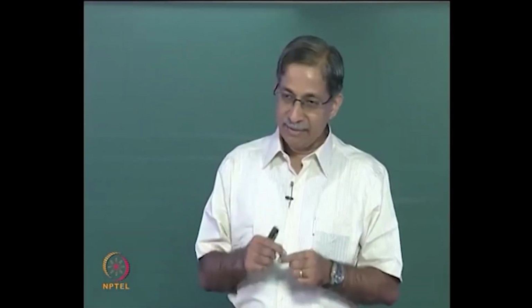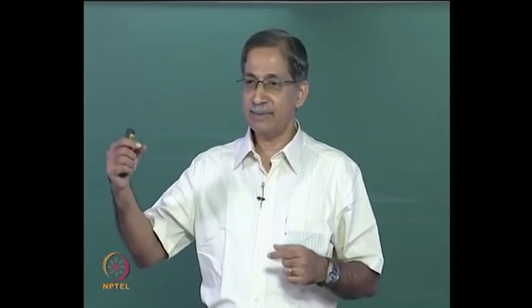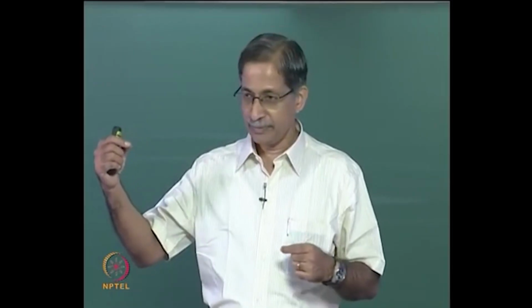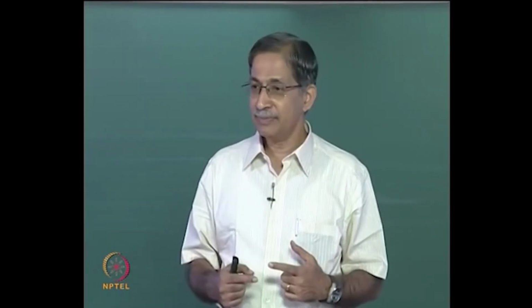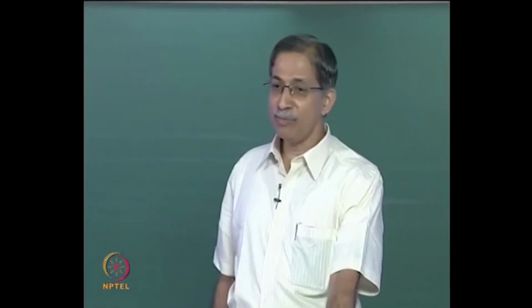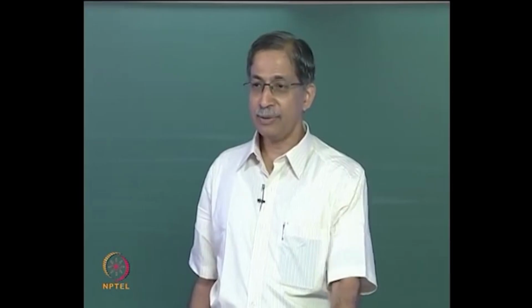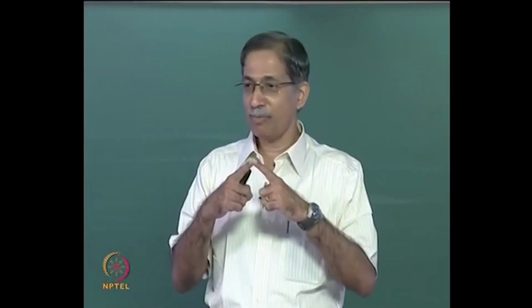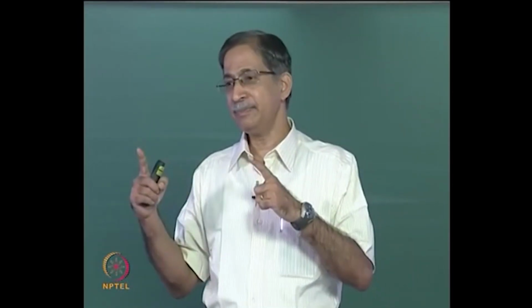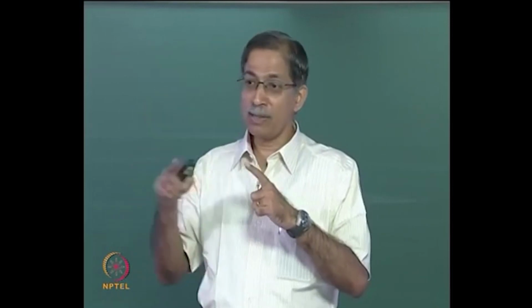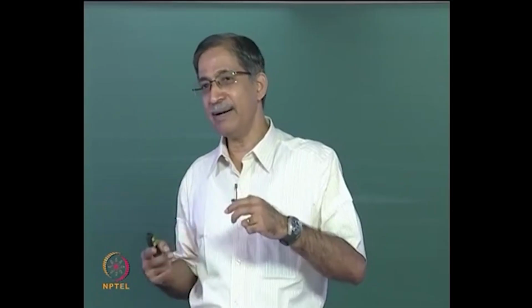Similarly, every member in this truss can elongate, the 2 joints can move. Compatibility demands that whatever movements you get at the element end levels must match the movements you get in the structure. So 2, 3 elements joining at one point will have the same movements in the global coordinate system, but in the local you have to resolve them into their relative components. That is compatibility.